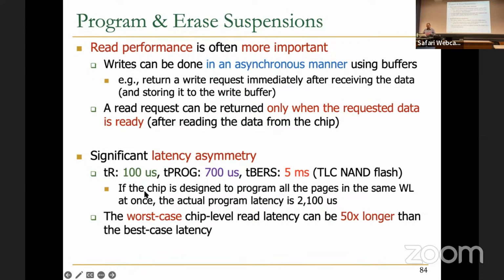If the chip is designed to program all the pages in the same word line at once, like we discussed in the past, when we have TLC and want to program all 3 pages at the same time, this program latency is around 2,100 microseconds. So you can see that the worst case chip-level read latency can be 50 times longer than the base case latency. If you are unlucky and your read is queued after a program or erase, you need to wait a lot. That's what we don't like.